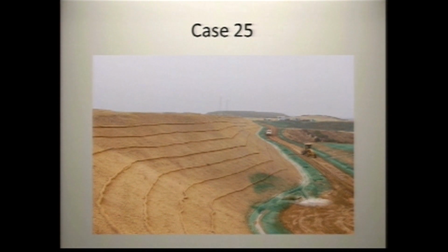but I'll tell you what, it has absolutely performed beautifully through 2 seasons. This whole huge slope that you see has wattles at the right interval, but then they also sprayed it with bonded fiber matrix. Down in the flatter areas, they use wood fiber mulch. You can see the green. And then where that grader is, they just went in and put in an inch of AC over that to keep the streets so they could drive on them and check all the erosion controls. So they tried to cheat the system at the start, but came back and did an absolute bang-up job.